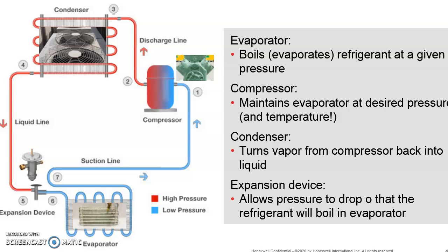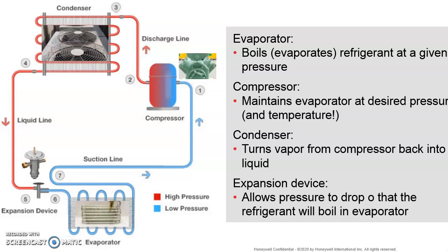Now, if you had an infinite amount of liquid refrigerant in a huge cylinder that was free and was okay for the environment, you could just run it through the evaporator at the correct pressure, let it go out, and you wouldn't need anything else. You'd be refrigerated. Kind of like the propane tank when you're cooking. That pressure is being released, it gets cold. If you open that propane tank and wanted to cool a room, don't do this, it would cool the room as long as you had refrigerant in there.